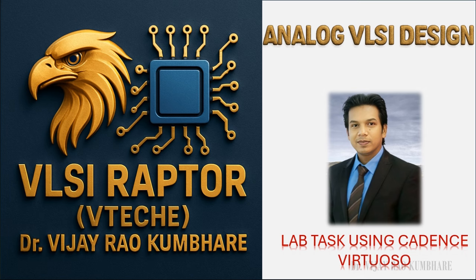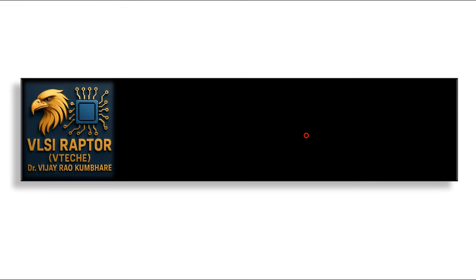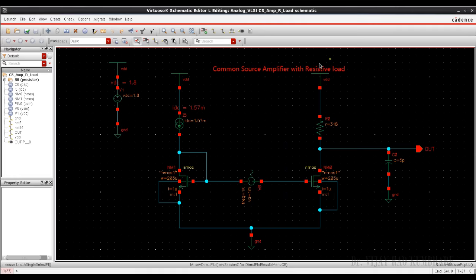This is Dr. Vijay. Today we will learn the common source amplifier with diode connected load using 180 nanometer technology node. In my previous video, we have already designed the common source amplifier with resistive load. So the same circuit we have taken here to implement the diode connected load. The only difference here is that the resistor of 318 ohm will be replaced with an NMOS with gate connected to VDD.